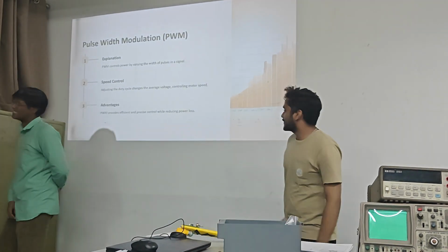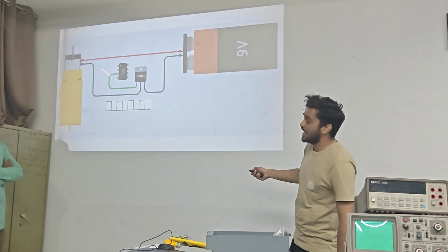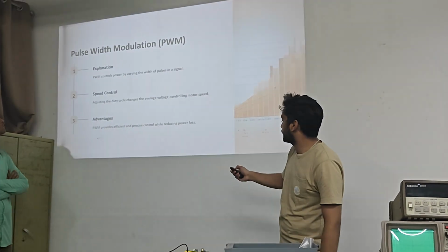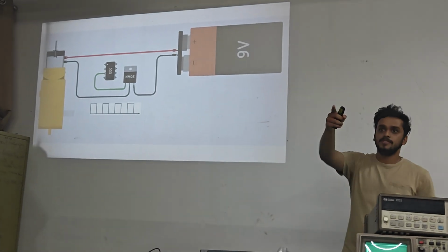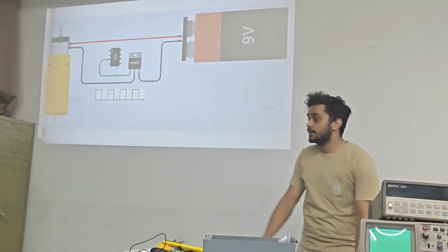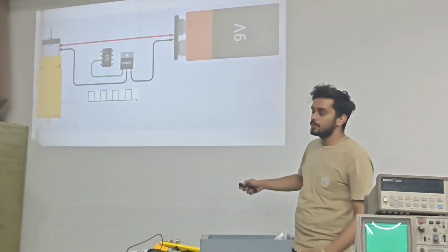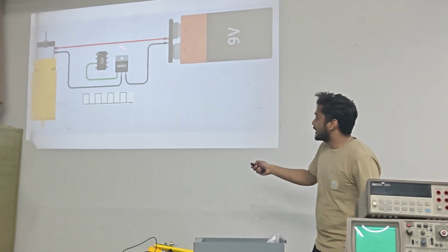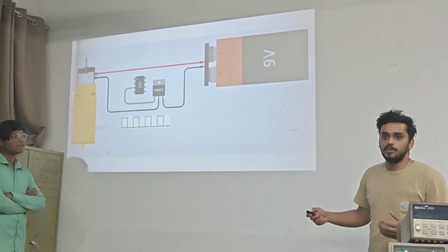Thank you. As we already discussed pulse width modulation, basically what we are doing here is this: the NMOS acts as a switch, and to control the switch, we are using the output from the 555 timer. Like this physical switch, we turn it on and off physically, right? To turn on the tube light and to turn off the tube light. But this MOSFET also acts as a switch, and we control that switch with electronic signals generated by the 555 timer. This switch can turn on and off more than 1000 times a second, so that will help us to control the speed of our motor.